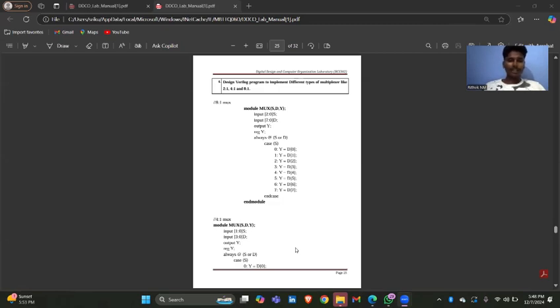So here I have declared a module named mux with 3 ports, that is S, D and Y, where S represents a selector input, D represents a data input and Y represents an output. In the second line, I have declared S as a 2-bit input signal, and it allows 4 possible combinations such as 00, 01, 10, and 11, which are used to select one of the 4 inputs in D.